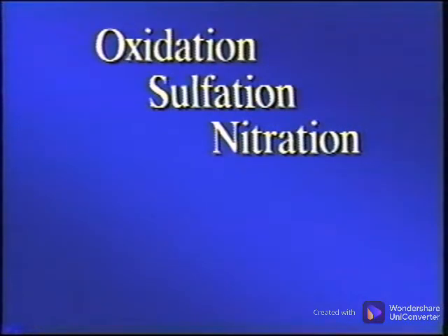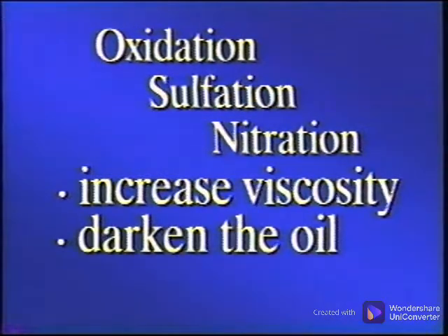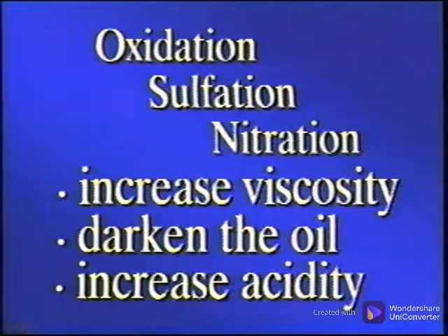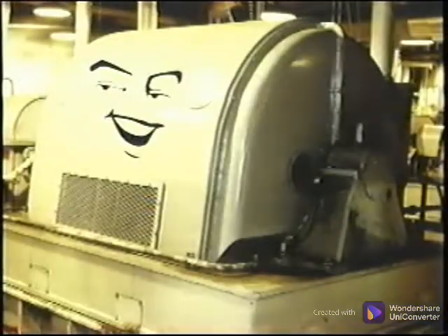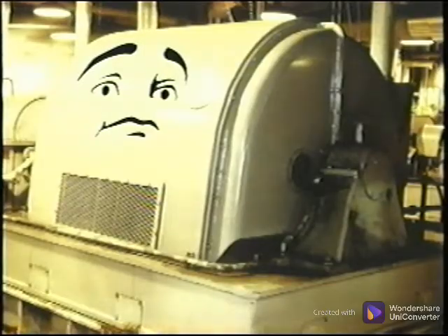Oxidation, sulfation, and nitration all increase the viscosity, darken the oil to a reddish-brown color, and increase the acidity of the oil. The increased acid in the oil causes corrosion to your machine, so that instead of protecting the machine, the oil actually accelerates degradation.